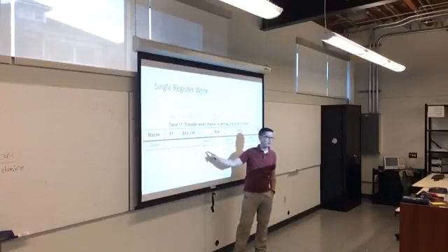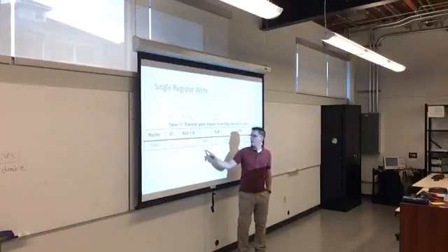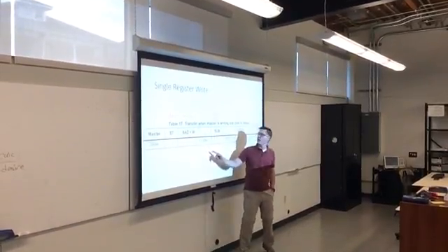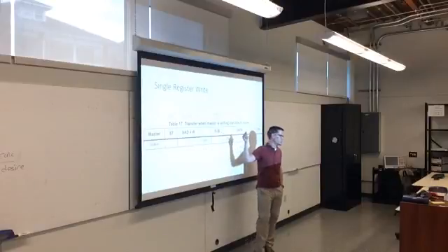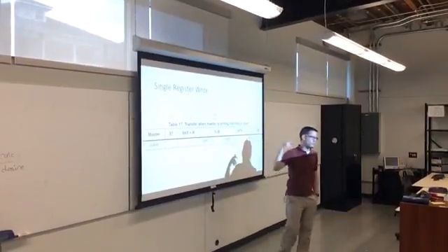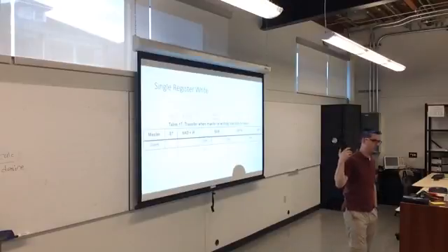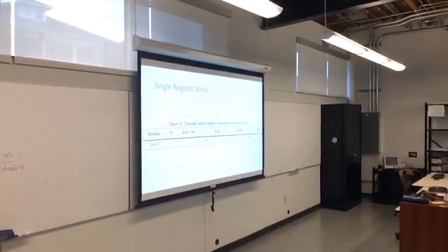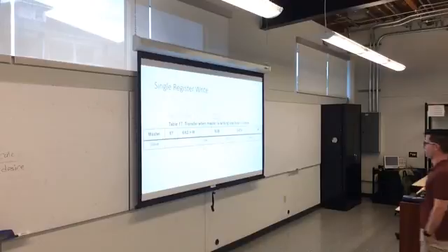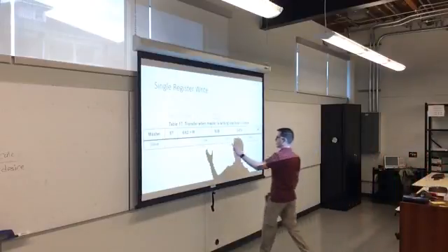For some reason, the documentation uses "sub" to mean sub-address, which is pretty dumb. I don't know. What the word sub in here is talking about is the internal register address that you either want to write to or read from. So it'll acknowledge, you give it the register that you want to write to, it'll acknowledge, you give it the data that you want put in the register, it'll acknowledge, and then you'll stop.